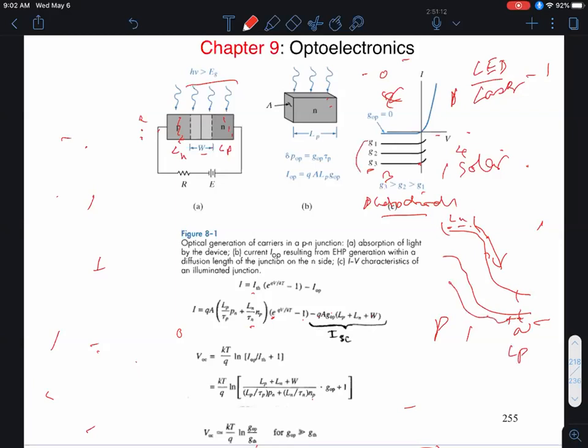And that's what I'm seeing over here. So you get additional leakage current. I'm increasing the supply of minority carriers in the reverse bias diode. And I'm basically increasing the supply over and above the black body radiation, which gives you G thermal. Okay, so now I only have G thermal, G optical is 0. That's the regular IV. But then with increasing photon flux, I get more leakage current. And obviously a measure of the leakage current is a measure of the photon intensity, the photon flux. So that additional current gives rise to this optical current on top of the regular IV of the diode,